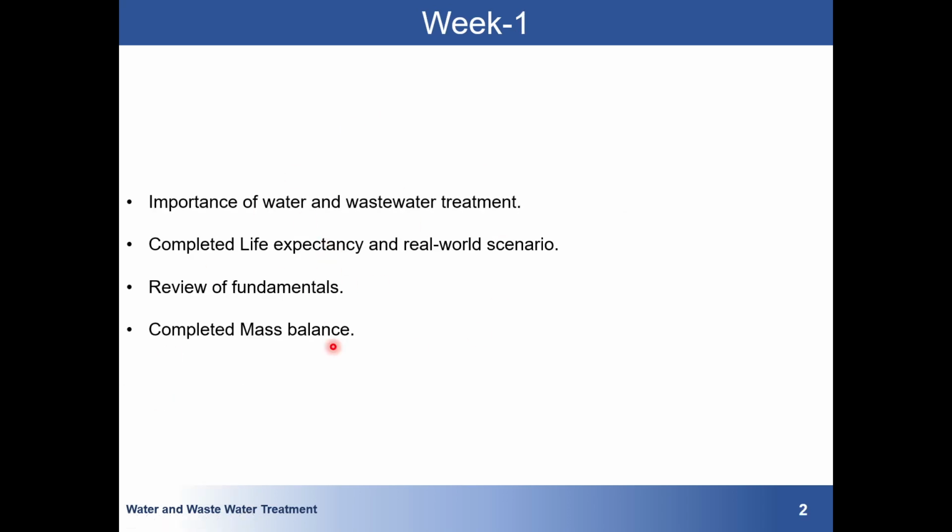On the first week of the lecture, there was some basic discussion about water and wastewater treatment, and you were given some tasks related to fundamental concepts like the mole. There were some questions related to this topic also, like chemicals such as calcium and sodium being added to the water, and you were asked to find the molarity. There were also several different drinking water parameters. Remember, for drinking water parameters you have to follow the drinking water IS code, that is IS 10500:2012, which is specifically for drinking water parameters.